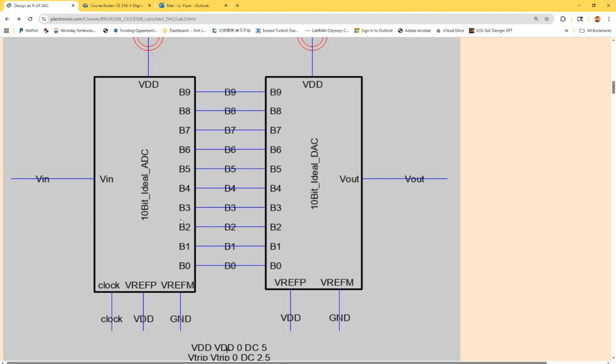But they are both power sources. For PCB design, usually we use VCC for some reason. I don't know why, but you just need to know that. When you see a VCC or VDD, you know that's a voltage source, whether in IC design or PCB design. For VSS, S stands for source. Source is the bottom terminal of the CMOS transistor, usually connected to ground.